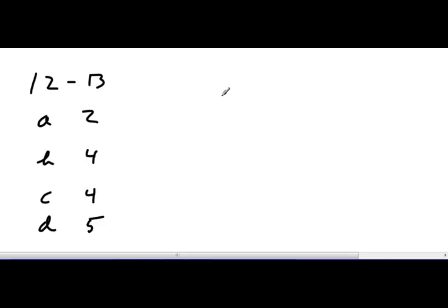All right, so if I want to divide by 2, I can do that with 1 flip-flop. I just showed it to you on the other page. If I want to divide by 3 or divide by 4, it's going to take me 2 flip-flops. If I want to divide by 5, 6, 7, it's going to take 3 flip-flops. 8 to 15, it's going to take 4 flip-flops.